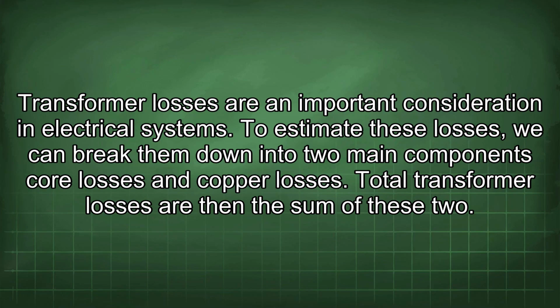Transformer losses are an important consideration in electrical systems. To estimate these losses, we can break them down into two main components: core losses and copper losses. Total transformer losses are then the sum of these two.